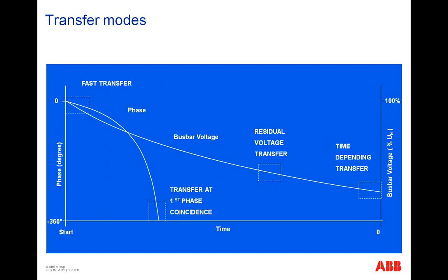After this time, this will be measured also by the commissioning. You will see all the motors running down on the bus bar, everything has a standstill. We send some load shedding signalization because, you know, if everything is connected going down, you open the main feeder breaker and it's closing the standby feeder breaker after 2 or 3 seconds with all connected loads.